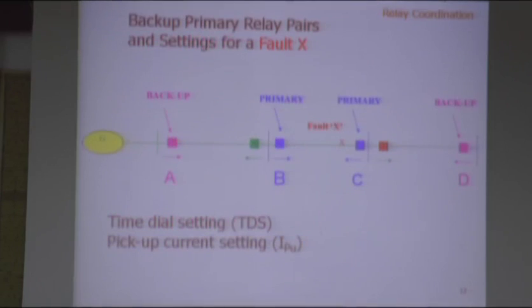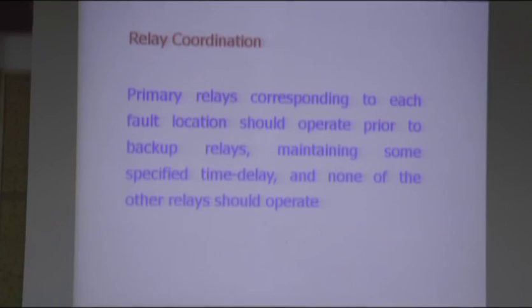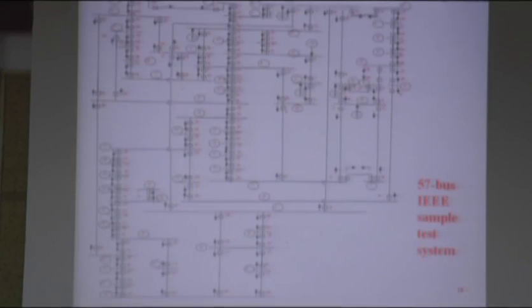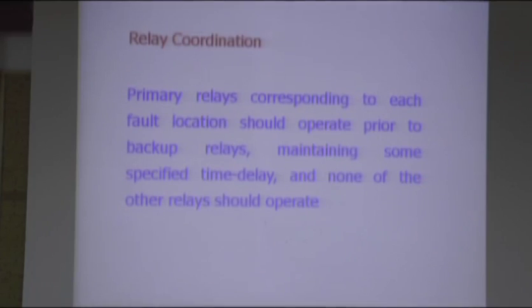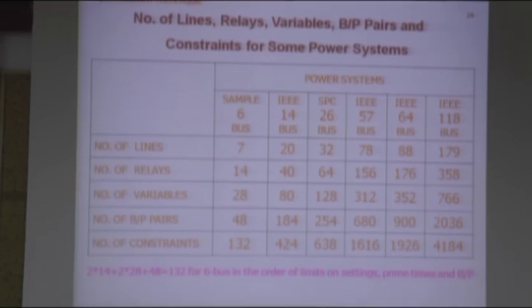So under this dilemma, for this small system and then for large subsystems, there are now so many relays. What is normally expected is that in a line there are two relays at either end. First of all, these relays should operate. Those are known as primary relays. And the circuit breakers at either ends in the adjoining lines are also there. They are supposed to operate if the primary relay fails to operate. That means they should come for backup protection only.